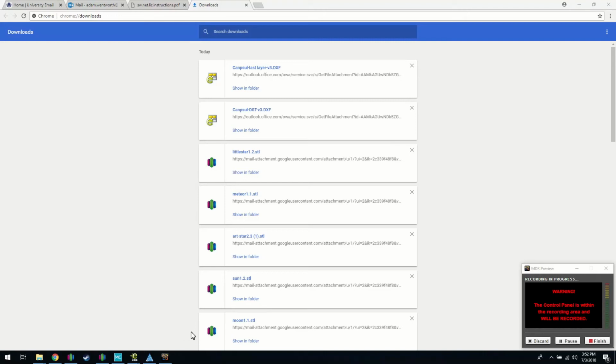Okay, this video is to show you the workflow, how to cut out a custom-made vector file. So what we've done first is to make a SolidWorks drawing file or regular part in SolidWorks where we'd like to cut out the outline of one of the faces. In SolidWorks, we will save that as a DXF file extension, and we have one of those saved here.